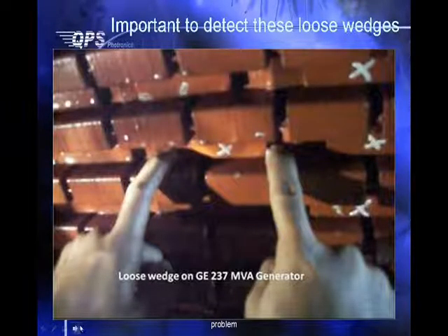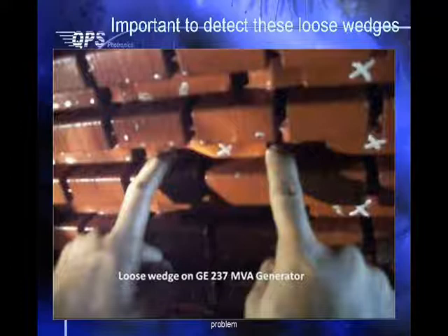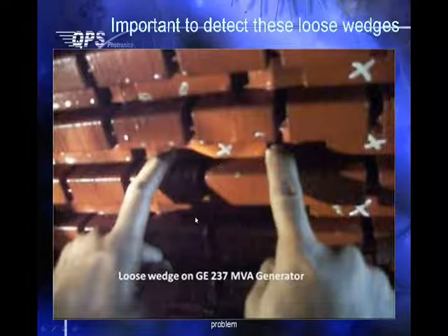In the last 50 years, everybody has been aware of this problem. So during a maintenance cycle, I mean a major one, they will take out the rotor and start inspecting. Now, there are 2 things you need. One, you need experienced technicians, well-trained inspectors, who can identify, just like the slide shows, a loose wedge. This gentleman puts an X at the location where they need to re-wedge it and make it very tight.